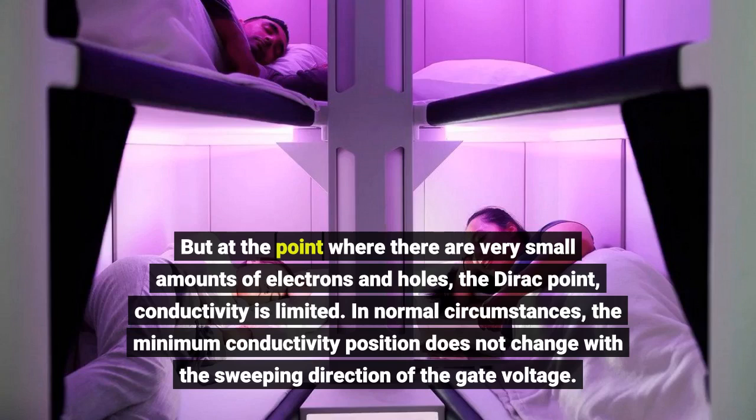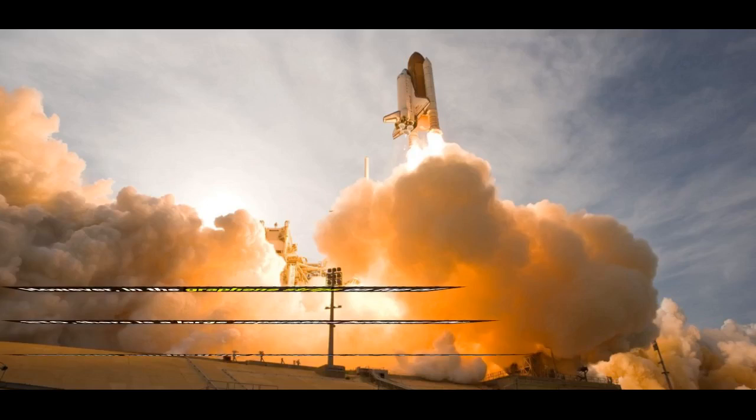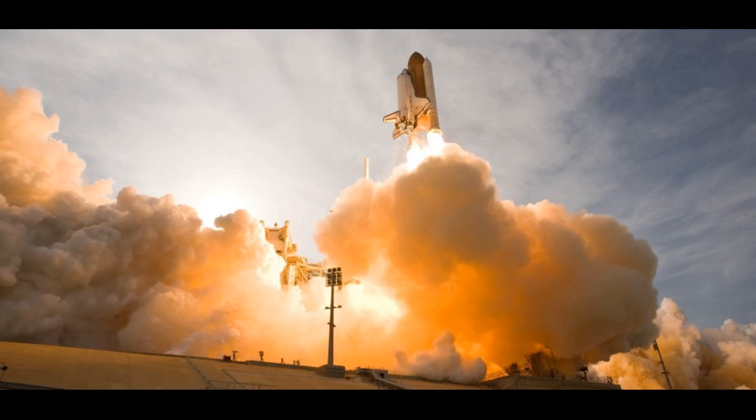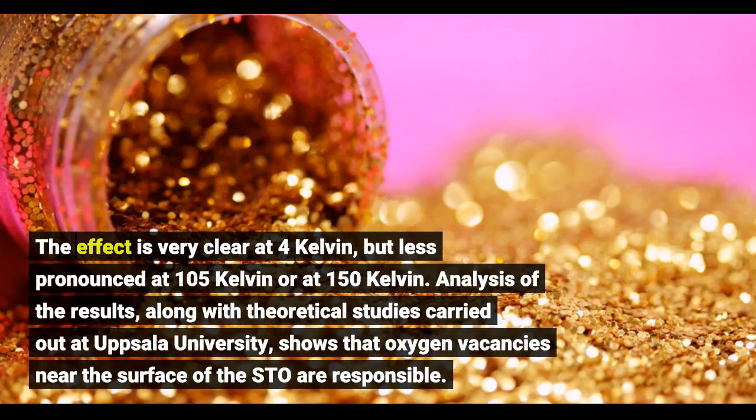In normal circumstances, the minimum conductivity position does not change with the sweeping direction of the gate voltage. However, in the graphene strips on top of STO, there is a large separation between the minimum conductivity positions for the forward sweep and the backward sweep. The effect is very clear at 4 Kelvin, but less pronounced at 105 Kelvin or at 150 Kelvin. Analysis of the results, along with theoretical studies carried out at Uppsala University, shows that oxygen vacancies near the surface of the STO are responsible.